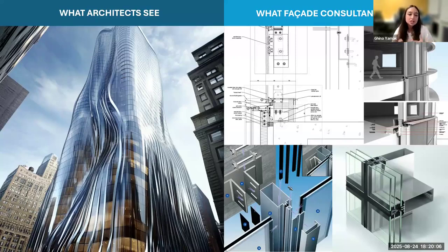And discussion starts to happen, but this is what architects like to sell. This is what gets sold to the developers and to the decision makers, right? Dreamy renders, very optimistic geometries, very challenging geometries. The height is okay, we can tackle the height with the right wind load, but how the geometry plays its role with the wind load and with its surroundings? Is it standing alone, or is it part of an urban context? How are we going to access this tower to actually install the facade?